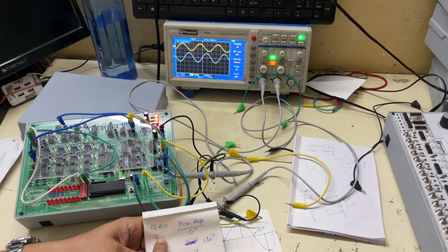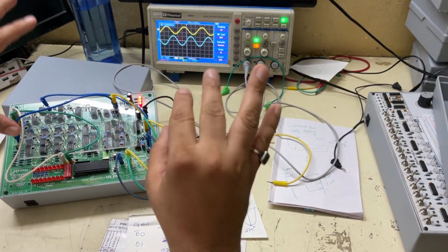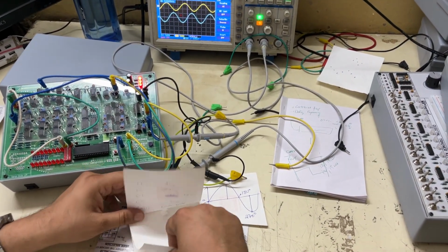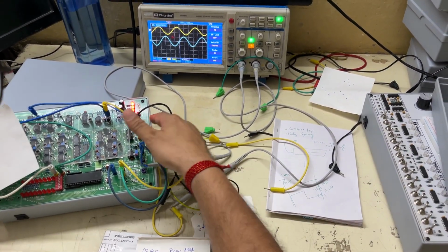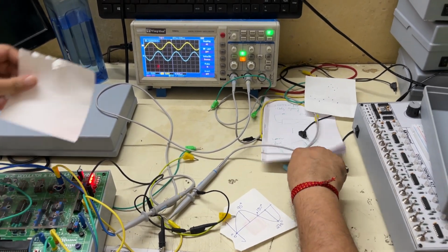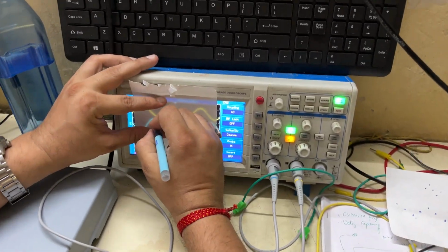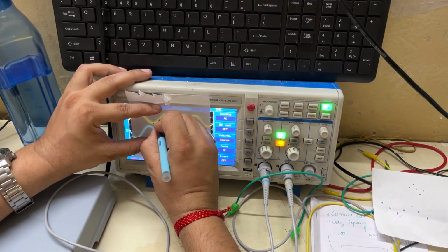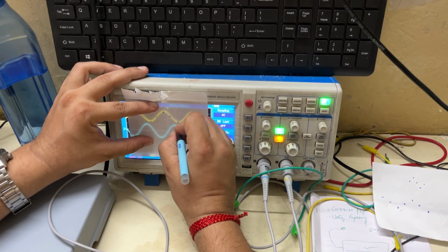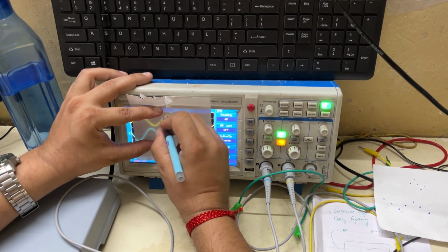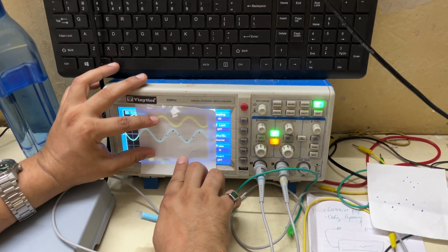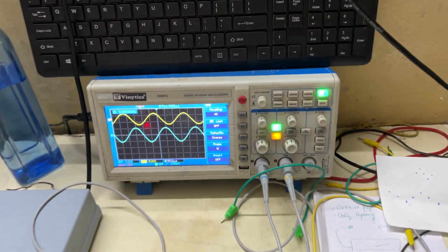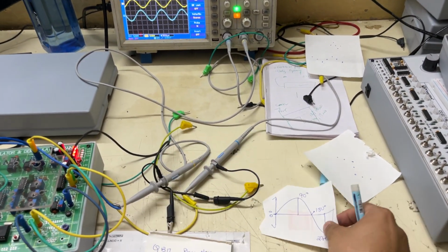Now first, let us consider the first scenario of the Q bits being 0 and 0, the phase shift is 0. The meaning of the phase shift 0 is that if you trace the input by a simple method of generating dots, let me show you. Even on a DSO, there's a very simple way: bottom, top, mid, mid, bottom, mid, and top. So now this is a complete sine wave. If you superimpose that on this, there is no change. So considering that this is our 0 0, there is no change, the input and output phase are the same.